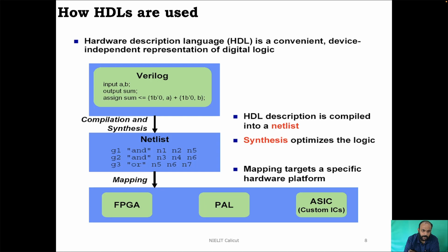So we write a Verilog description in the RTL way, or the synthesizable way, and put it for synthesis. The synthesis tool reads and infers your Verilog code. It finds out what should be the equivalent hardware structure, or the gate level netlist, as we call it. The gate level netlist seems like another textual file, but it describes the gate level composition of your design. You can see an example gate level netlist here.